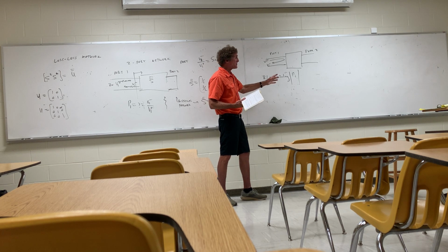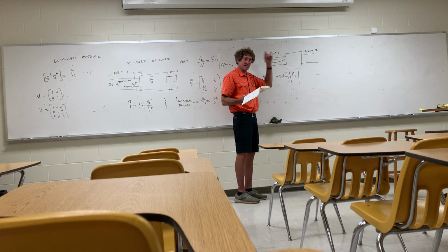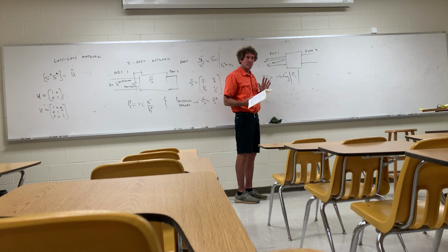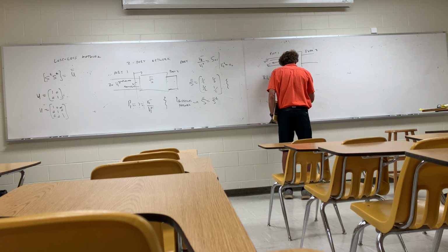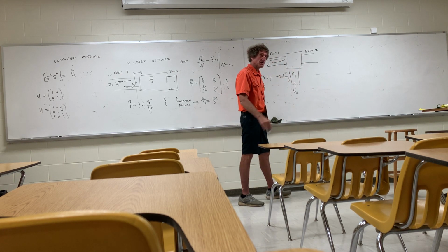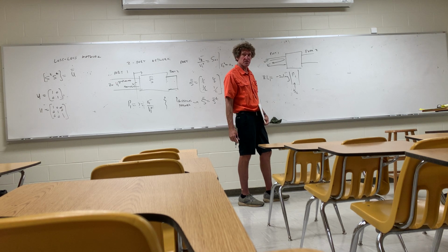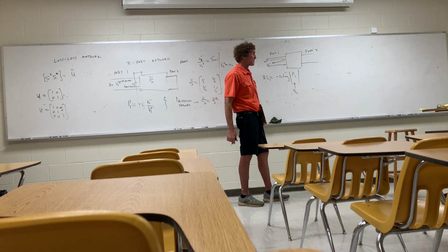Now, yeah, if there is some complication like that short circuit I showed you in the beginning, then you would have to get the true reflection coefficient with that short, and then take minus 20 times the log of that. But I don't really want to spend time on the odd situation. This is generally return loss for any port. And you might as well just make a little note here. This is S_ii. So it is a reflection coefficient, or it's the S parameter for that port, either 1,1, 2,2, 3,3, whatever.